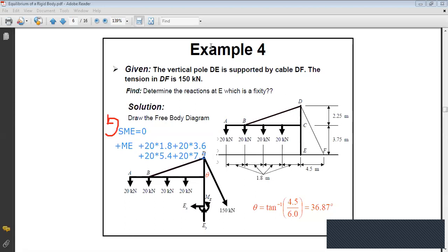Okay, so if I look at my figure, this is my force. I have two methods to find the moment of this force about E. Or I divide it into two components. So the first strategy is to say I will divide it into X and Y. And I already found the X and Y components, because the Y component will not produce a moment about E since it's passing by point E, okay?